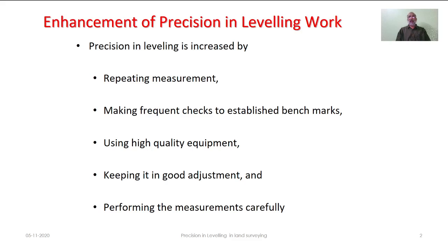Similarly, in leveling work, you are expected to start the work from a point of known elevation, which is nothing but the benchmark, as well as you are expected to close your work on a certain benchmark. On a stretch, on that particular run, there could be many benchmarks. As you have the readings on these intermediate benchmarks, it will apply frequent checks on the process that you are going through.